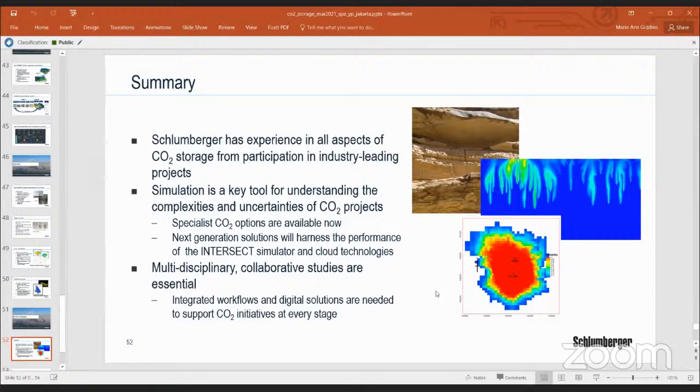The comparison between the cost of building a new well, working over an existing well, or simply using an existing well with minimal alterations. Typically, when people are looking at CO2 completions, they need to be either very high quality steel or fiberglass. And we also need to think about the cementation around the well. So CO2 acidified water from CO2 operations can actually destroy some of the cements that are used in wells.